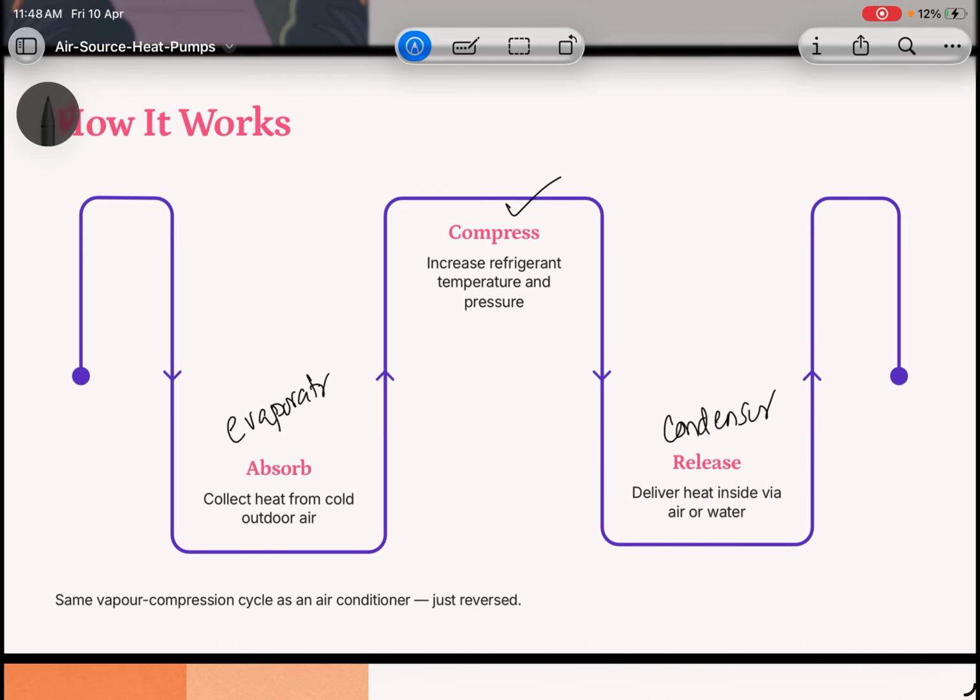This machine is similar to your refrigerator, where you have two heat exchangers. The condenser is the place where you get the desired heating effect, and the evaporator is located in the surroundings or ambient, and extracts the heat QL.